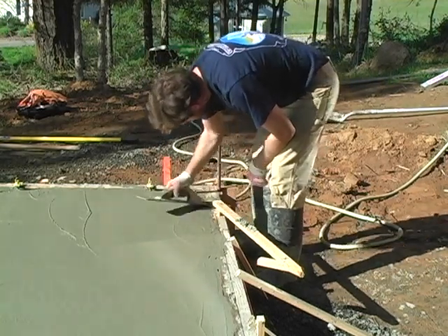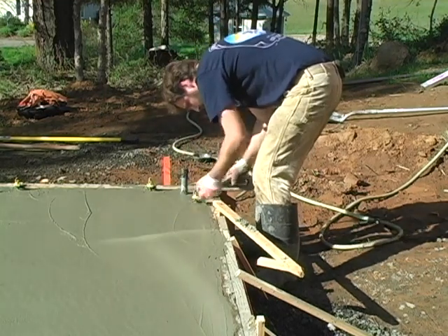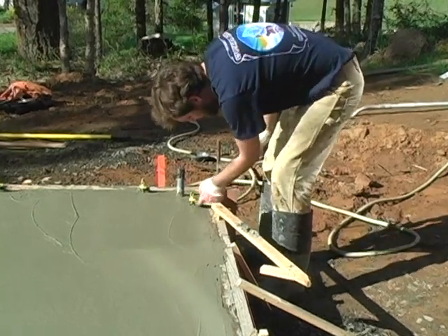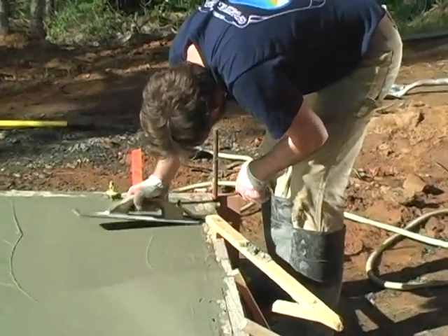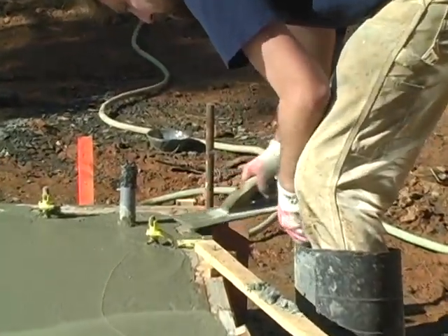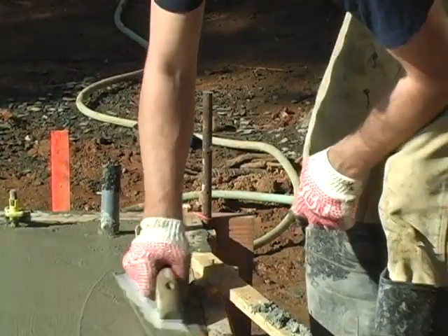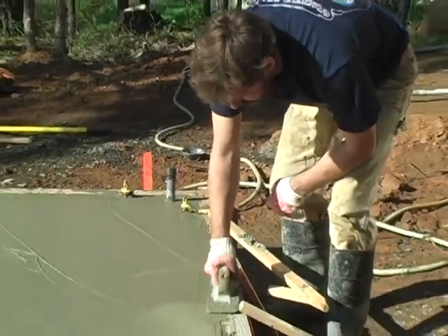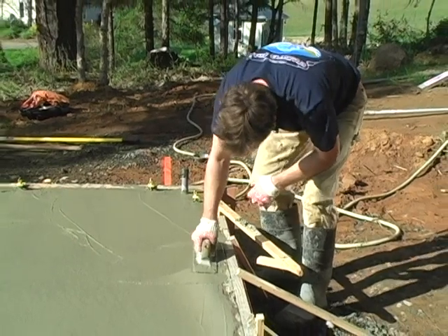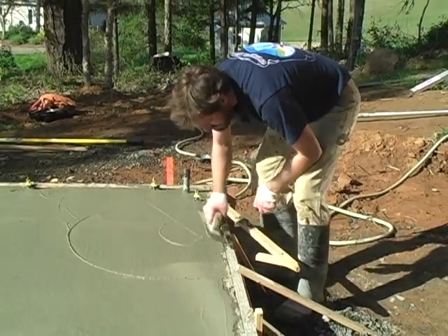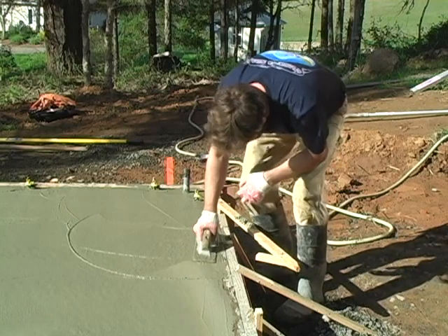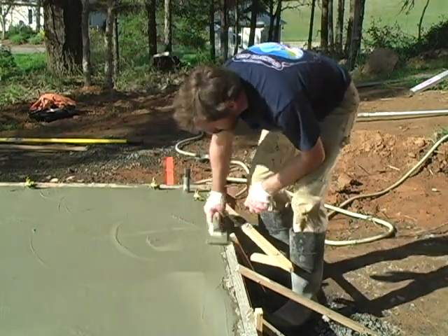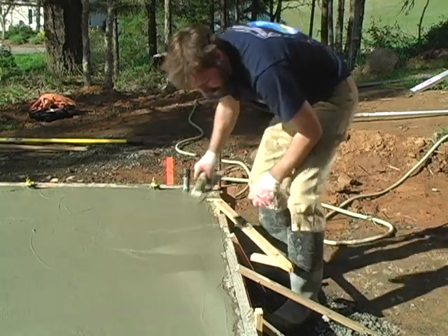Now it's really good to get underneath these anchor bolts or any other obstacles that you have in the way, because your plate needs to sit down on top of these, and if you've got a bunch of concrete popping up here, it's going to make it really difficult to get your plate to sit down flat. So a little attention around those edges is a good idea. And this is starting to set up pretty well now. So when I've got some spots where I need a little extra mud, I can put quite a bit of pressure here. Make sure I get everything in place.